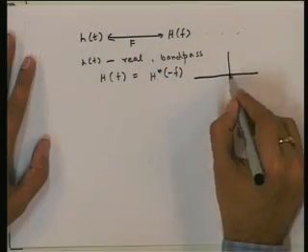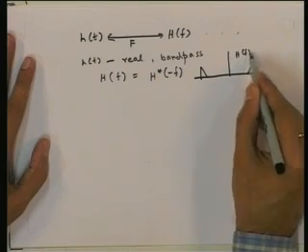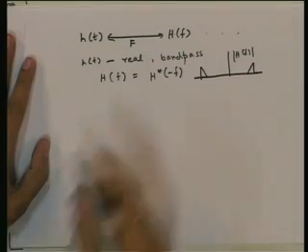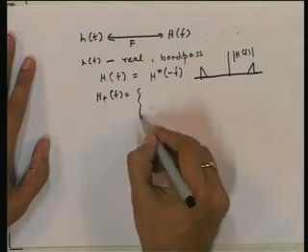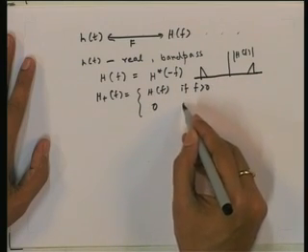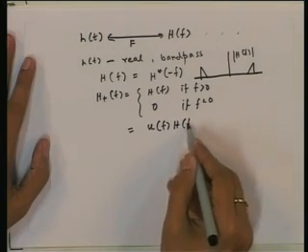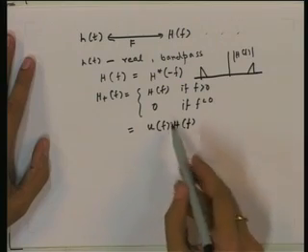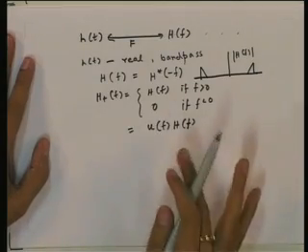Okay. Now just like we did for the bandpass signals, suppose this is H(f), and we are drawing only the magnitude. Just like for the bandpass signals, H plus of f is, take only the positive side. So basically H(f) if f is greater than 0 and 0 if f is less than 0. This you can also write as u(f) times H(f). Here for bandpass signals we actually had 2 times this, but here we are not doing that for some reason, which we will see later.